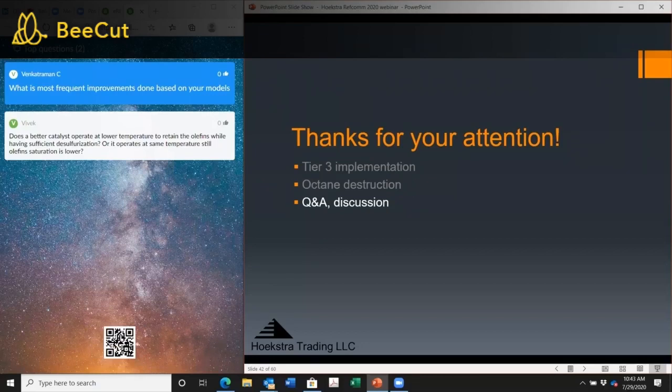George, this is Bucci Golapudi again. If I make a comment here, aromatics saturation is a very difficult reaction. It's a very highly exothermic reaction, and that reaction doesn't take place so easily. My understanding is when it comes to hydrodesulfurization, olefins and diolefins are easily saturated and sulfur is removed very easily from those compounds, but not from the aromatics.